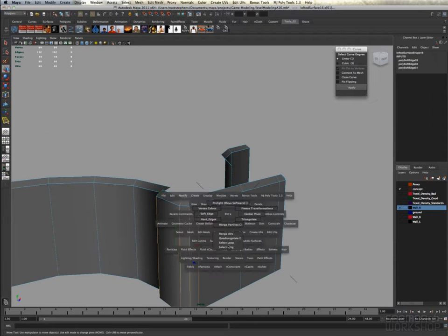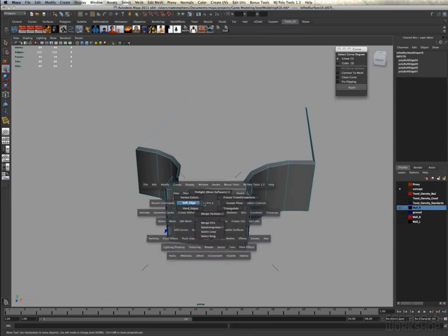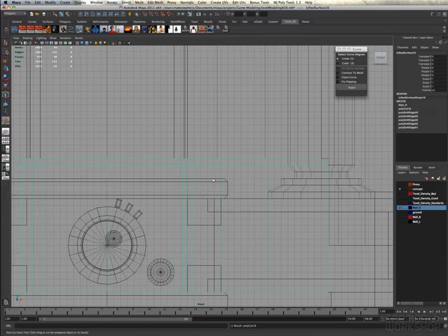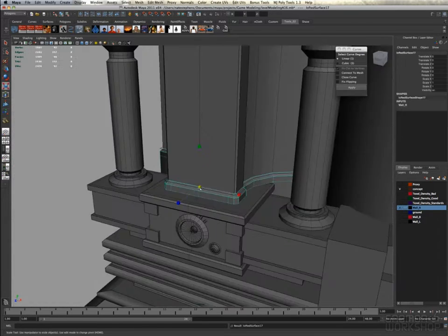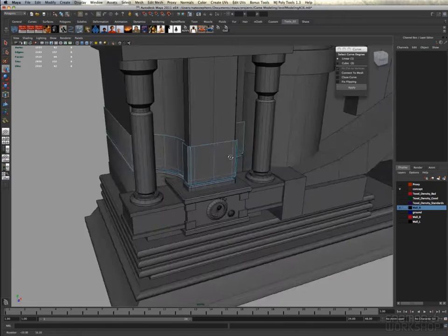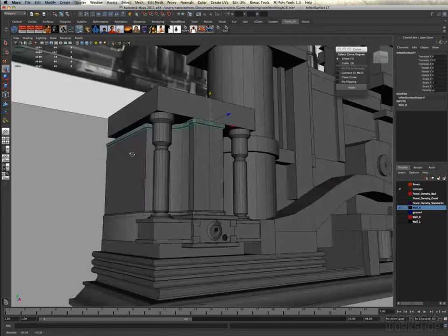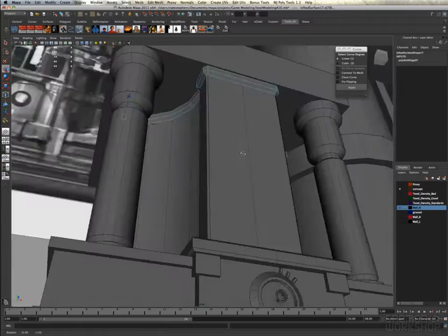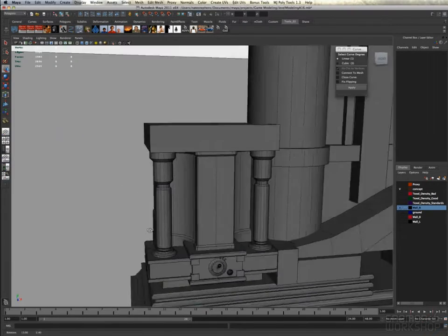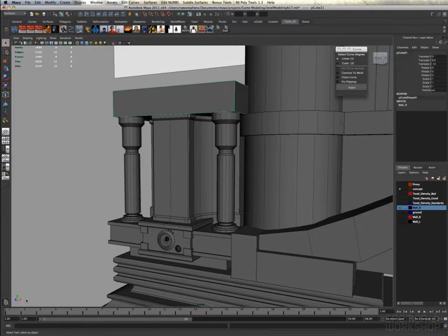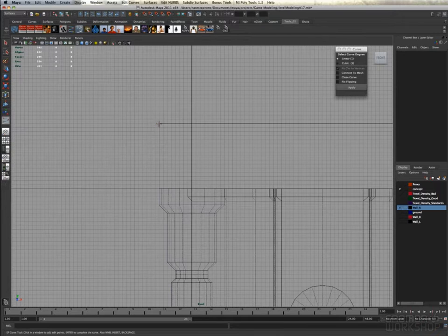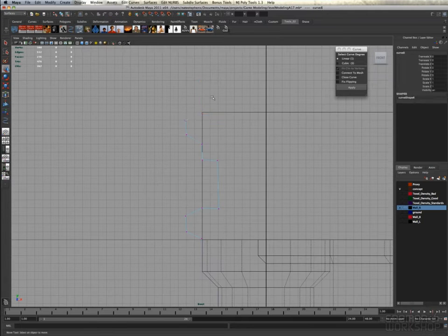And you'll notice that the way I'm building this piece was by creating a curve off the edge of the piece on top of it and then offsetting that curve and then doing some lofting. And now I'm duplicating the object and mirroring it just so that I have the same piece on the top and bottom. Which when I think about texturing, I know I'll just have to texture one of the pieces and be able to use it in two places.